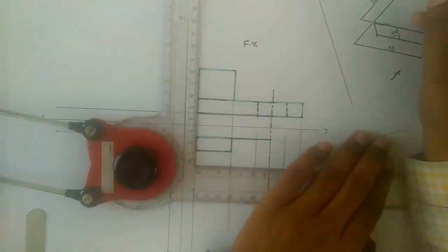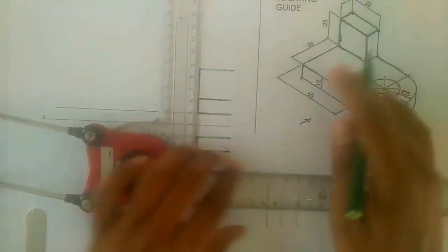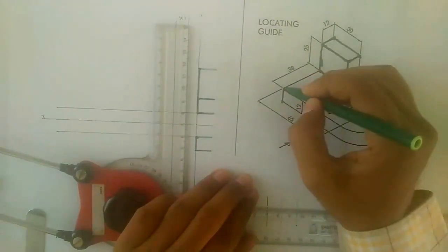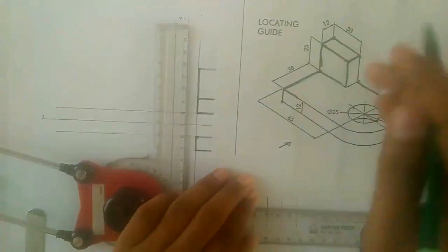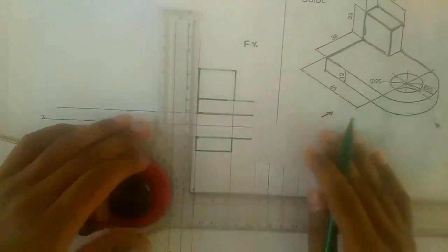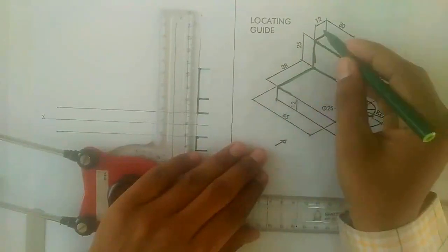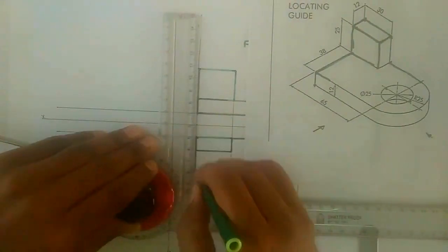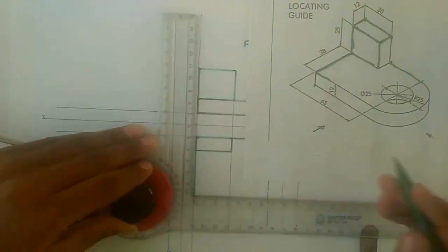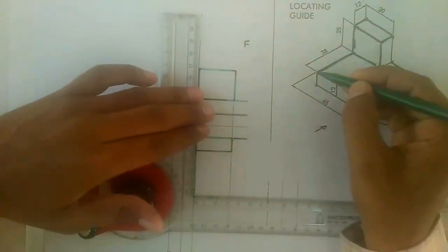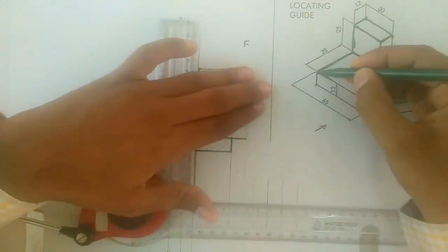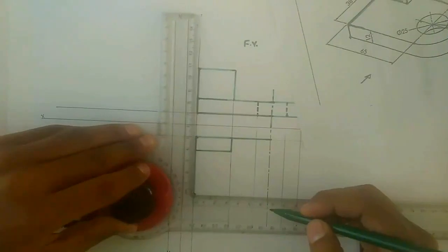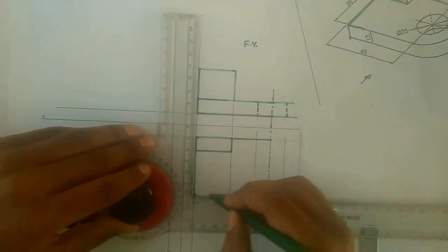Now when the observer looks at this object from the top direction, this point and this point are coinciding. So from this point we have to draw this 38 mm length. So the total length is 38 plus 12, that means 50. So I will draw this complete 50 mm length line. Then this point is here. From this point it is 65 up to the center. Again it is not required to measure. We have already taken projections. Draw up to the center line.